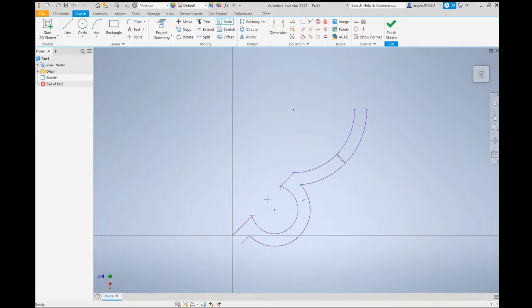Whenever there is, let's say, a dimension that you place there, it will actually restrict the intended position. Since Inventor is more or less like data or measures, it's more fixed with the inputs. So there's little to no room to make adjustments without considering it's part of a whole design. So if you want to adjust it and you don't really care for the other items to be stretched out, you can just relax it if necessary.